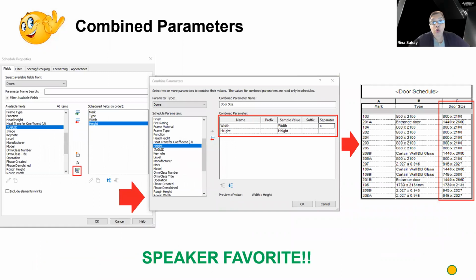Combine parameters, one of my favorites. What this does is allow me to take information from two schedule fields and combine them into one. For instance, in a door schedule, you would have a field for width and a field for height. I could take width and height, and using the combine parameters tool, put them together with a separator. And that would give me the door size in one field.